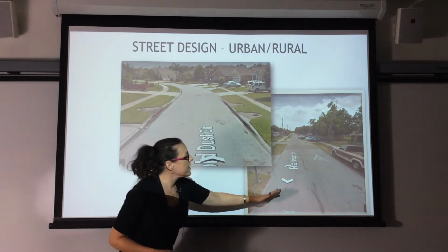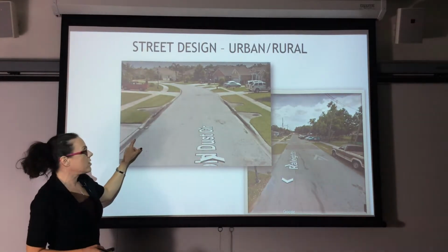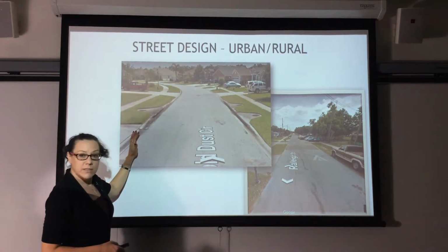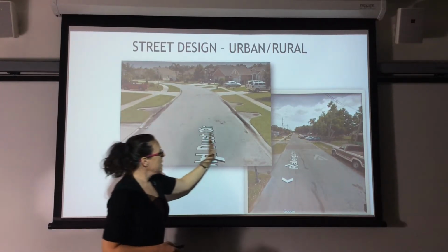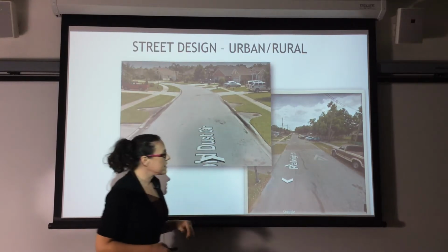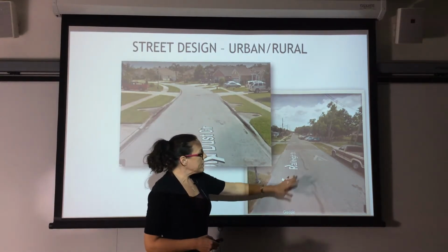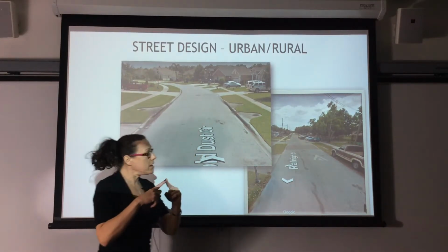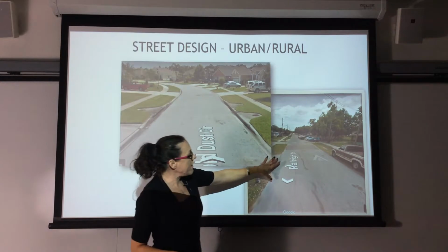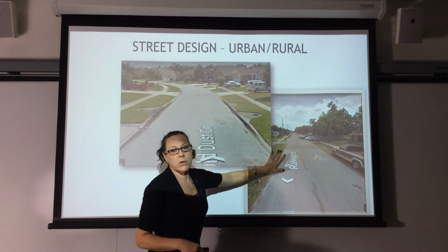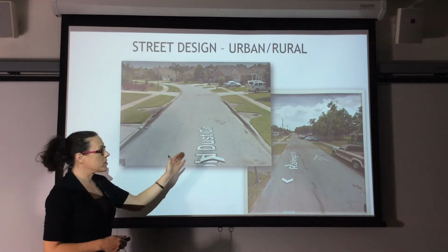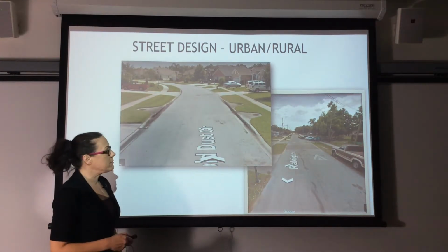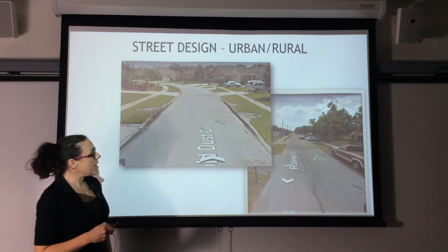The difference between this design and this design, you can see the curb and gutter. This has a cross slope center lane, cross slopes down and drains to this inlet. It drains downhill and goes to this inlet. The same with here. We typically have a crowned section, meaning the center line of the road is a peak and goes downhill. But notice that we have no curb and gutter. That means all the water goes into the grassed area and drains along the grass. And you can see that the road dips, or the driveway dips a little bit, almost along with the sidewalk.